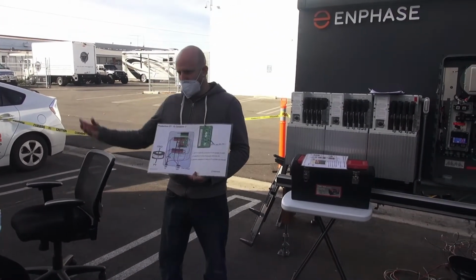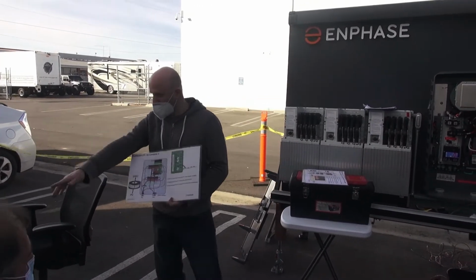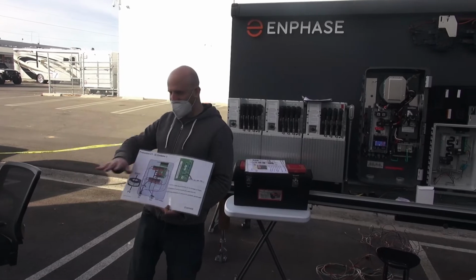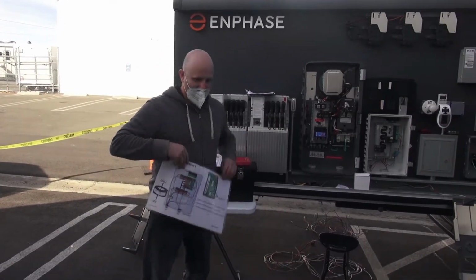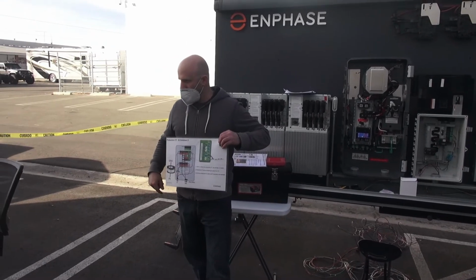If you buy this separate Envoy, you have to do that wiring yourself, but it has to land on the P1 terminals like you just said. Okay, easy, right? This one's easy, I think. Do not put that L2 wire through there, right?